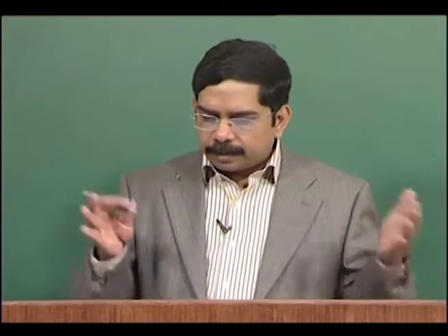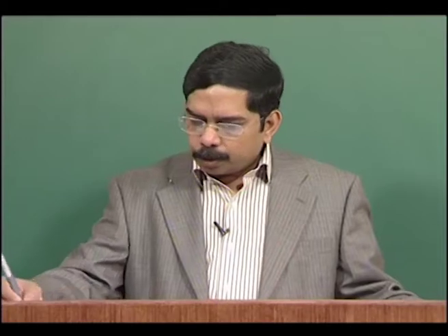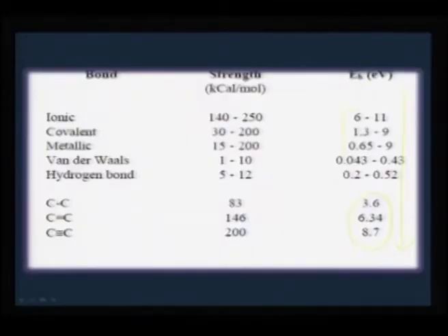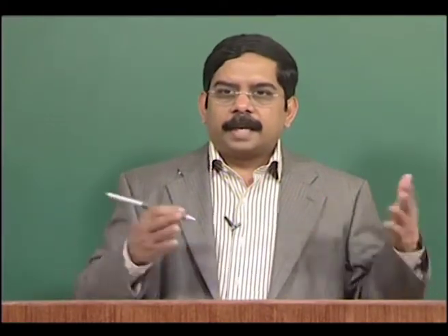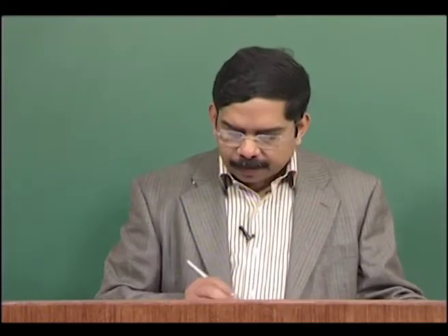So you need to have this idea, and also you would find out that the binding energy is more for ionic materials than covalent, than even metallic materials, but those which are governed by van der Waals force and hydrogen bond, those can be easily broken. So from these numbers we can see that, depending on the choice of the laser source, you can actually extend the ablation of material from ionic material down to organic.